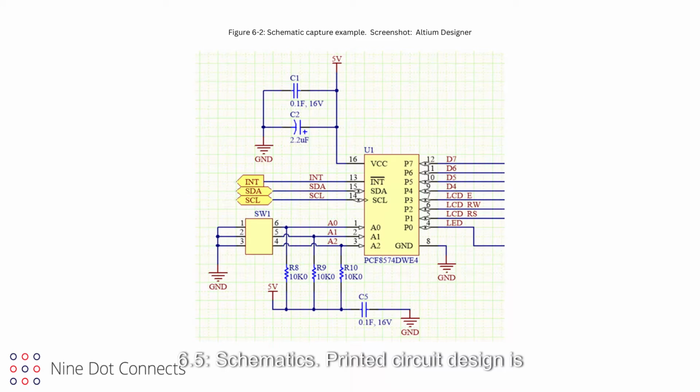6.5. Schematics. Printed circuit design is accomplished in an EDA tool. Although there are a few other options to create designs, an EDA tool is the most preferred and efficient method by professional designers. Designs start with the creation of the schematic, and guided by the specification. Schematics are dimensionless representations of an electrical circuit, consisting of symbols which represent components. The ANSI/IEEE Standard